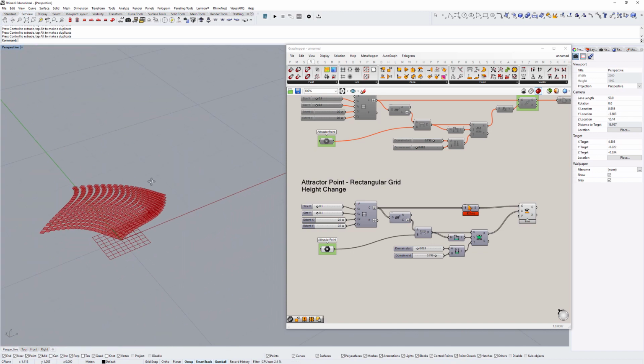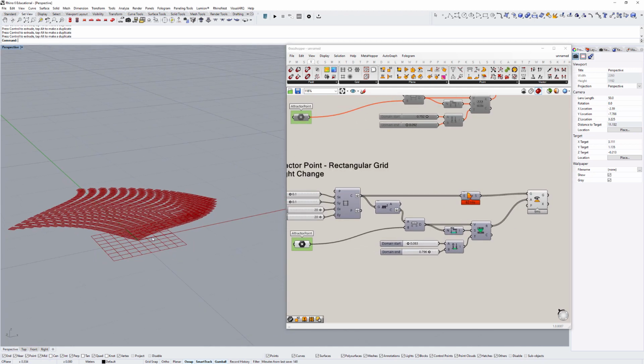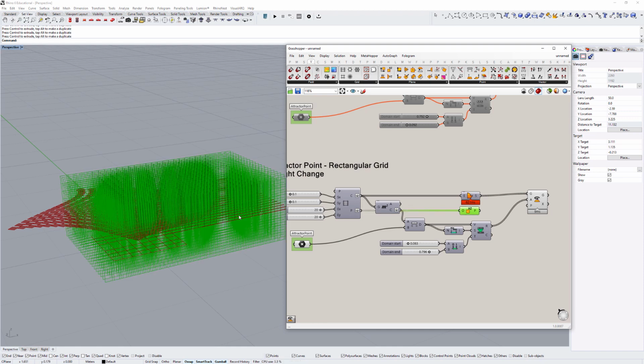It's not really working. That's because we still have one more input, which is our rotation plane. Let's rotate the panels in the X and Z direction. So at the moment you can see on the ground there's a plane there, which is representing XY. We want to make a plane that is within the XZ. So let's type in XZ. Let's take these points, put them in the XZ, and they're the planes.